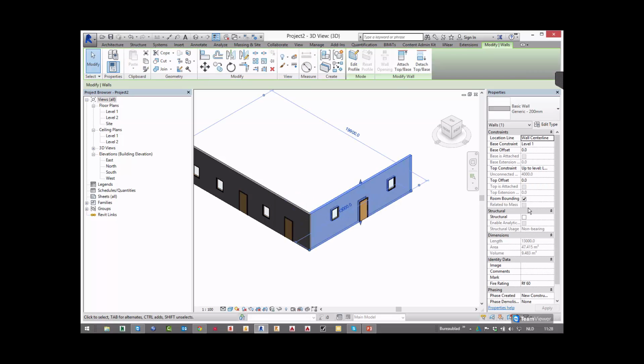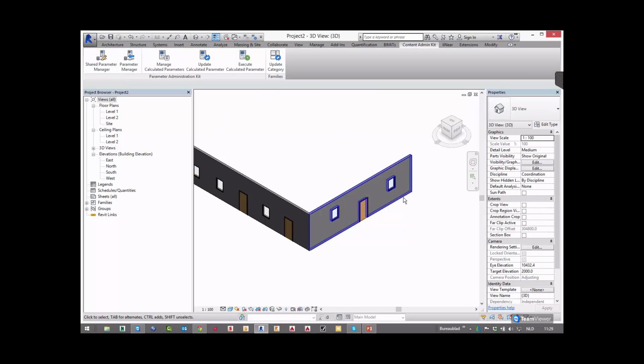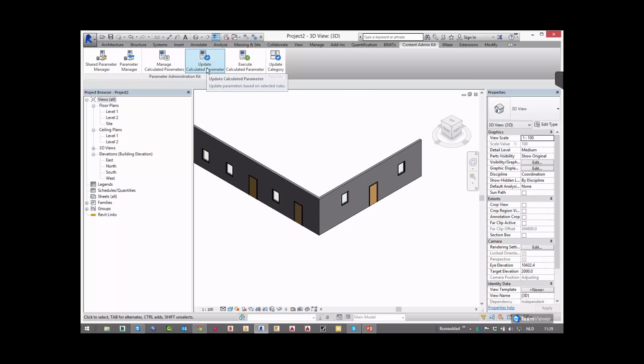So when you change something, I want to say, okay, this is RF 120. You have an update tool. So it doesn't automatically update its values, else Revit will be checking every time everything you modify, so that's not possible to do.